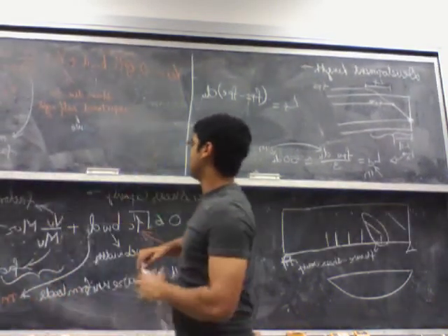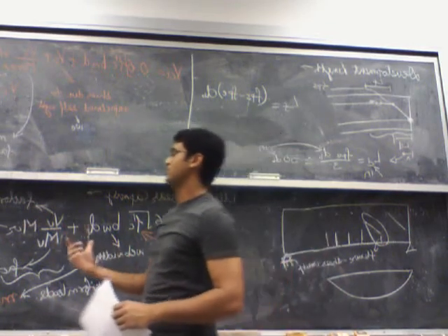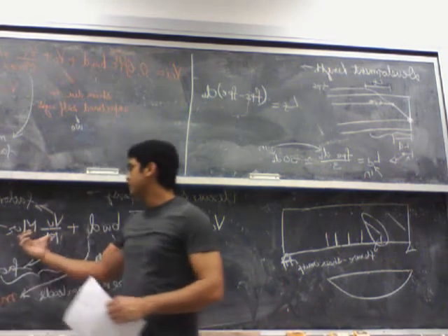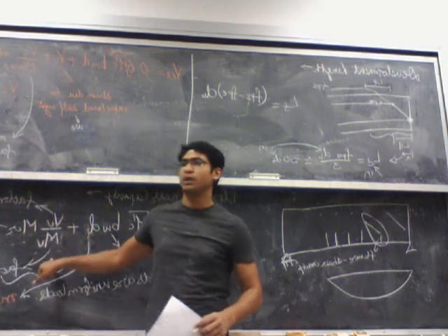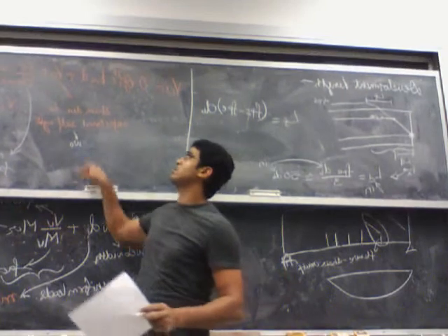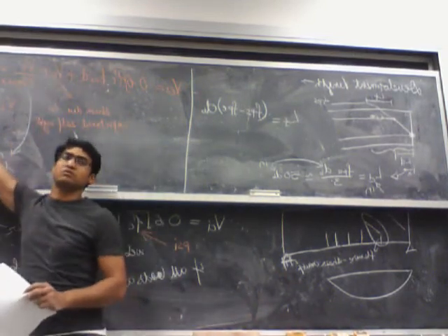So these two formulas are actually exactly the same. The only thing is, if all the loads are uniform loads, then you can simply use this, where you have all the loads factored and you find Vu and Mu. If any one of your loads is not a uniform load, then you have to take the self weight separately and the rest of the loads separately.